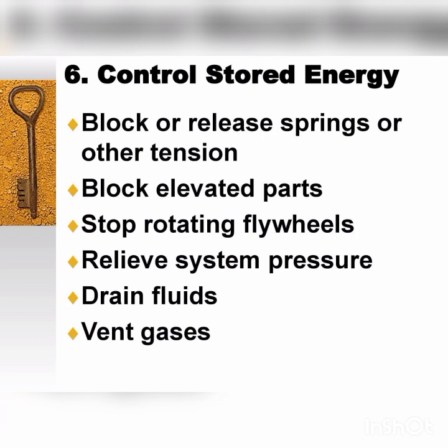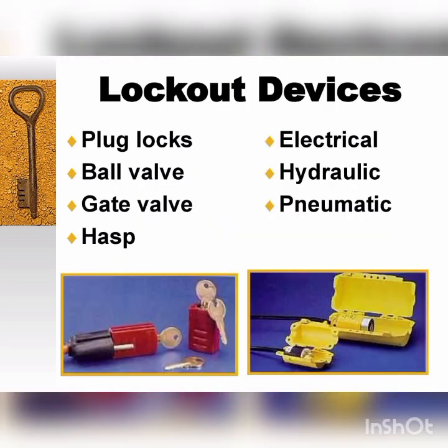And then you come to the last step, prepare for startup. When you have done the maintenance job, you need to again make sure that the equipment is properly connected with each other, the sources are removed, and all the areas are properly restored. Then you need to prepare for the startup of the equipment.